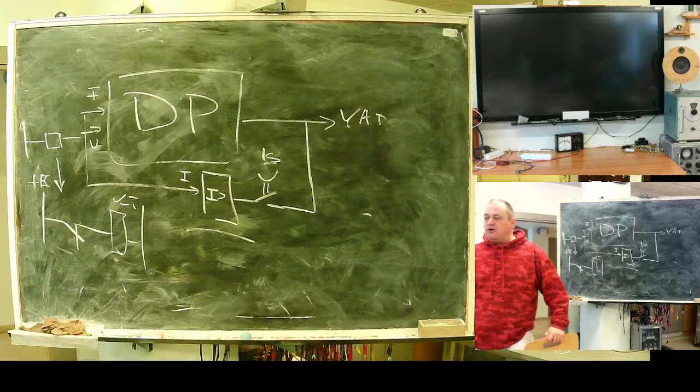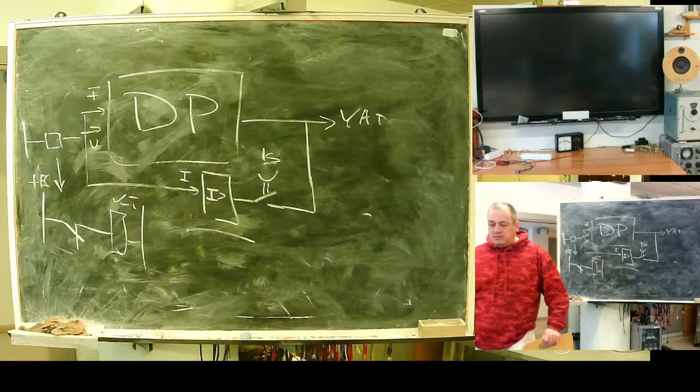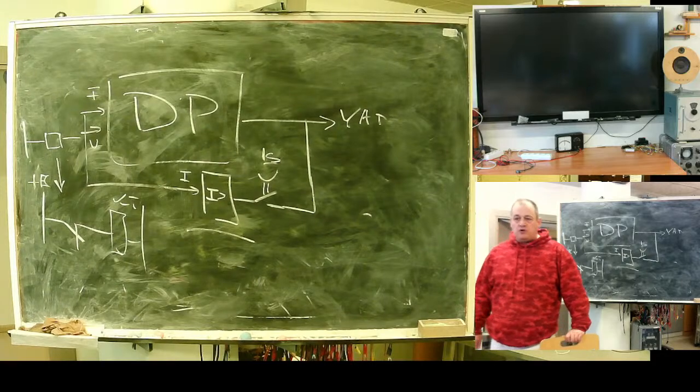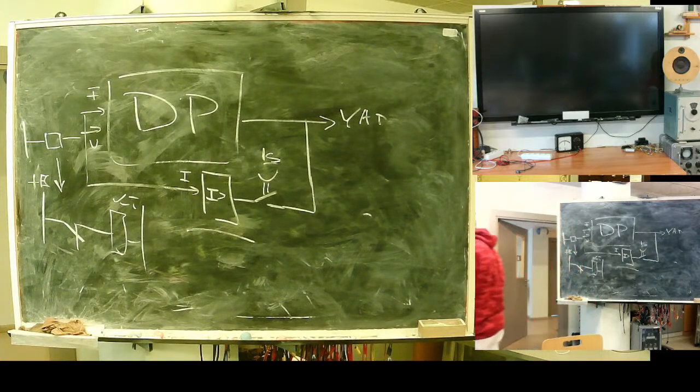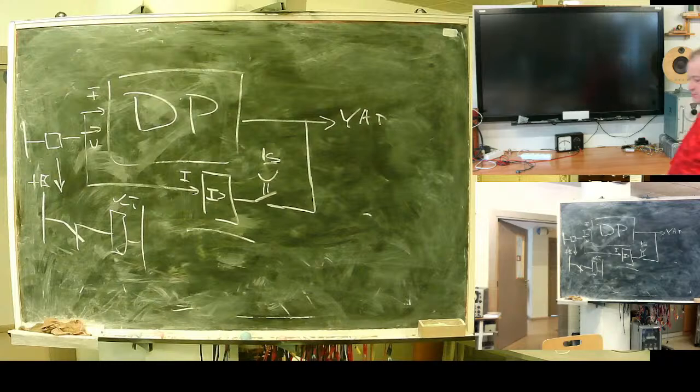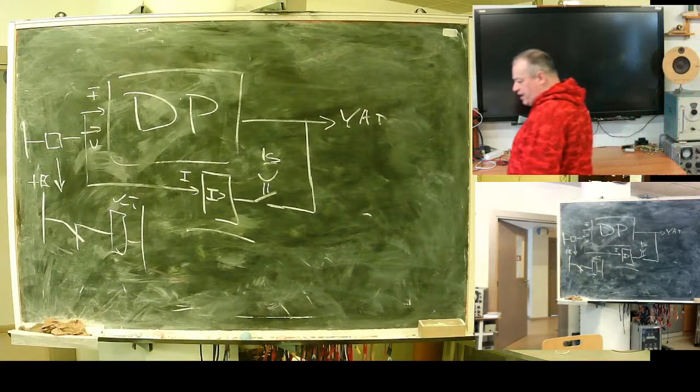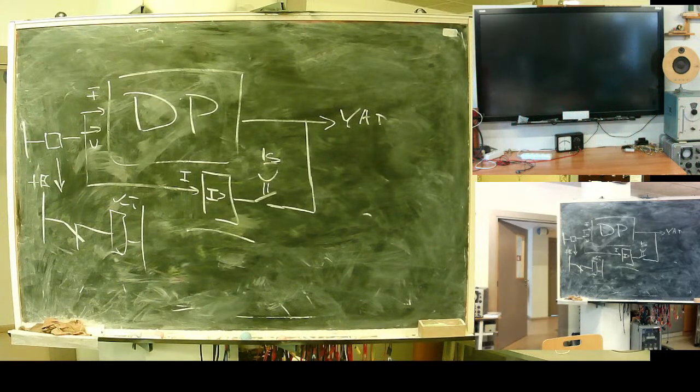After that, it will operate directly and this overcurrent protection is no longer needed. But for switch on fault condition, distance protection will fail if you have switch on fault at 0 distance.